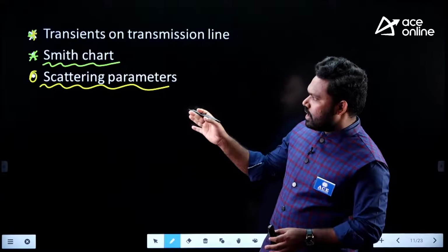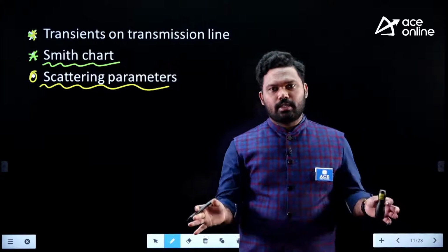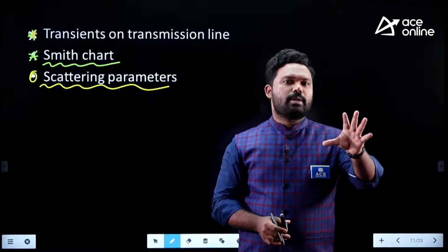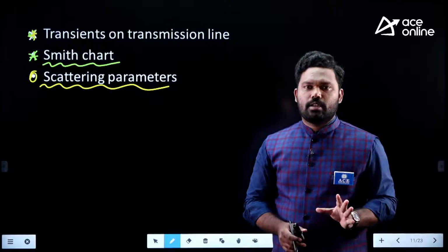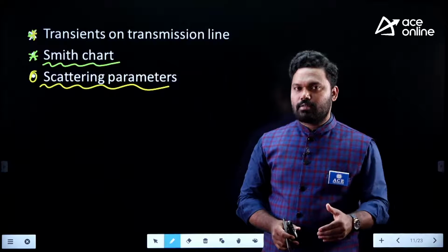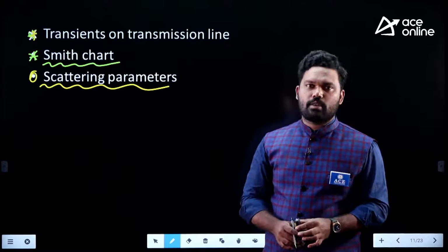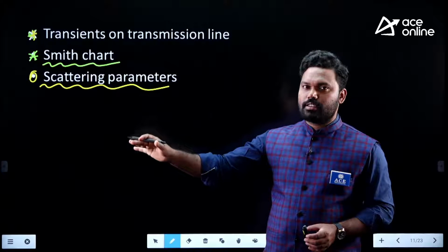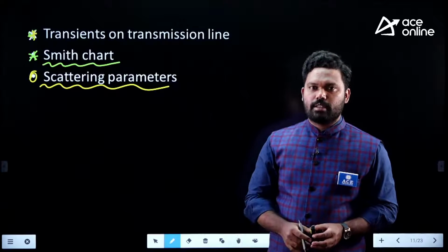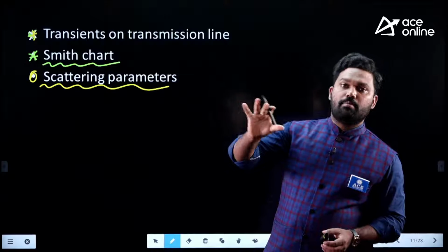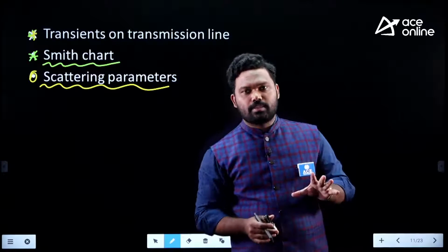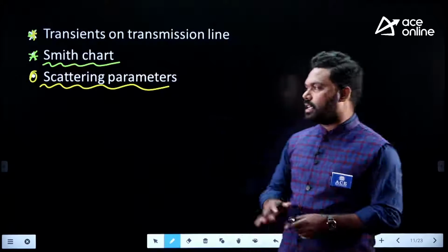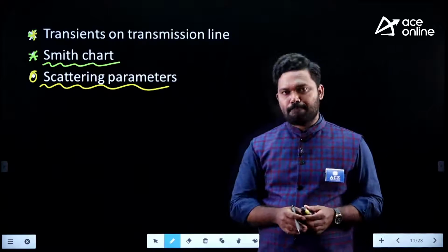But at high frequency, the realization of open circuits and short circuits is difficult. That is the reason why the scattering matrix comprises reflection and transmission coefficients. And you realize these scattering matrix parameters by performing a matched termination. That is the difference between your circuit theory parameters and S parameters.